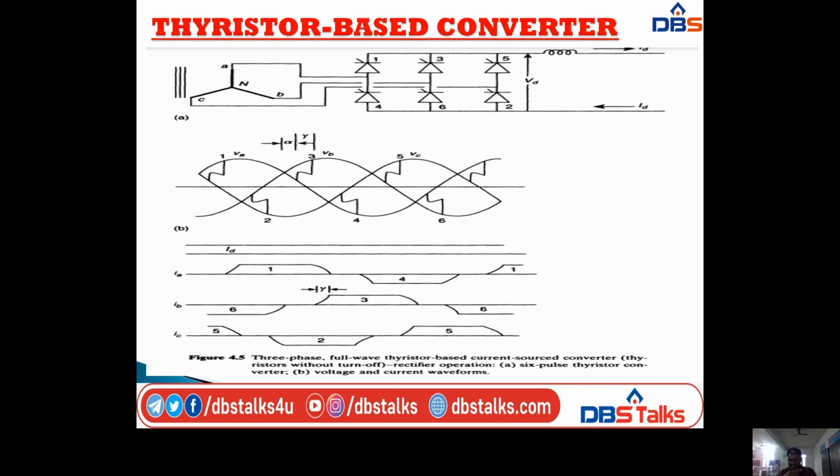In the previous class I discussed the three-phase full wave diode rectifier. At that time I took this same diagram, but here in the place of the diodes I am placing thyristors. In that one I used 6 diodes, in this operation I am taking 6 thyristors, numbered 1, 2, 3, 4, 5 and 6. The upper thyristors are numbered 1, 3 and 5, and the lower thyristors are numbered 4, 6, 2.